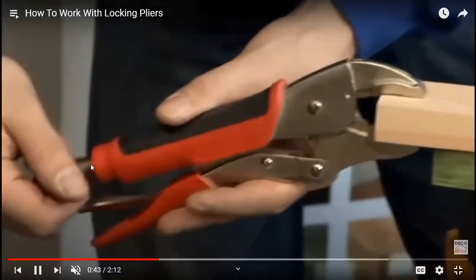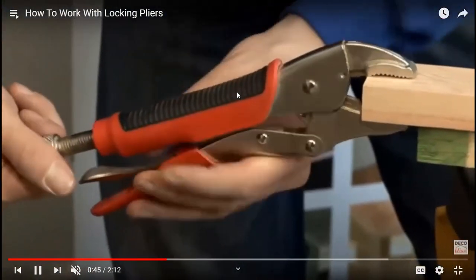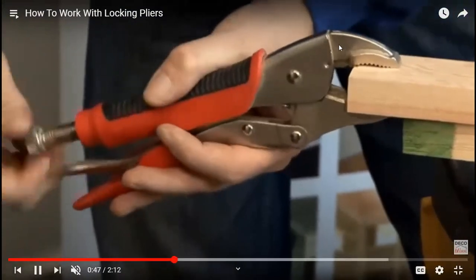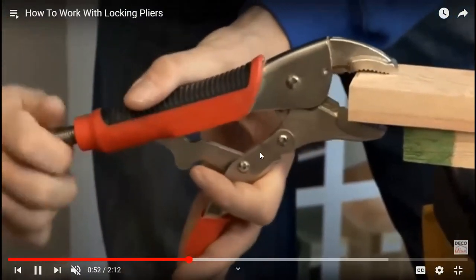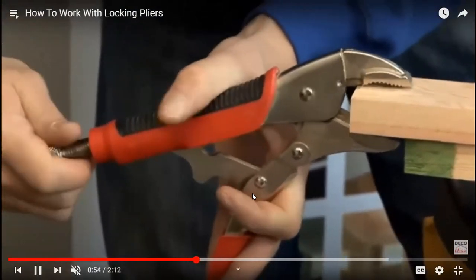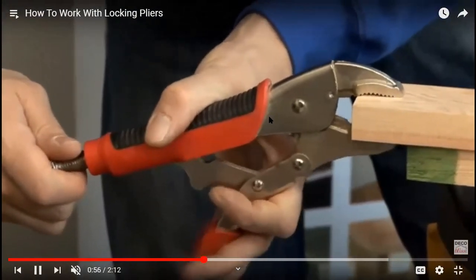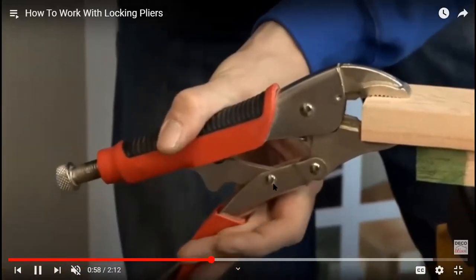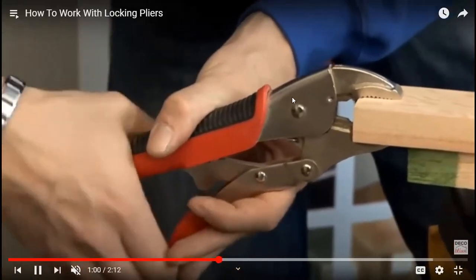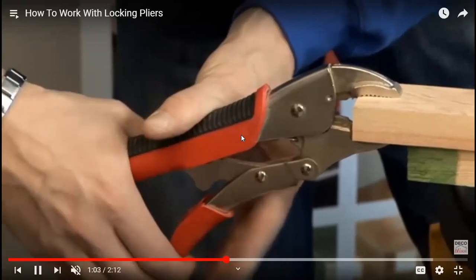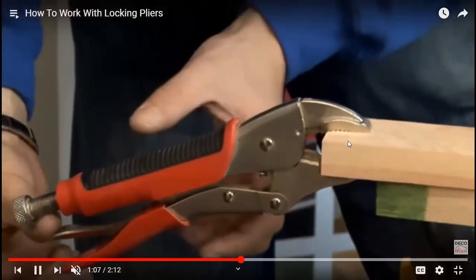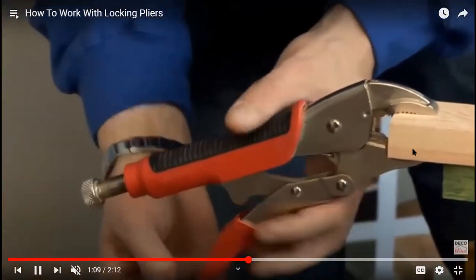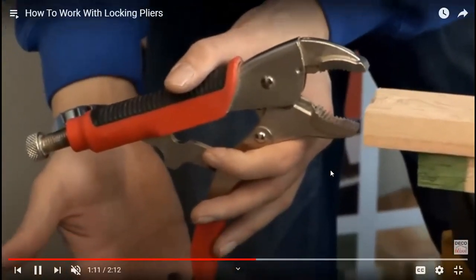So you can see here how this is moving. This is one rigid body. Then this can be considered as another rigid body, this as another, and this handle can be considered as another rigid body. These are connected through some joints. You can see some bolts and nuts arrangement here, and this is being used to clamp this particular wooden sheet, right? So this is one example of a mechanism.